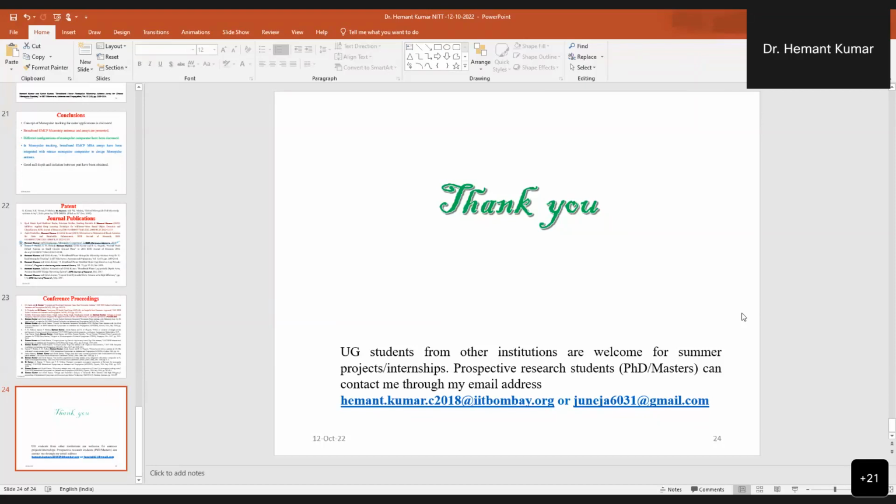There are other substrates available: apart from 5880, we have 5870 also, and there are two or three more substrates. Arlon is also one of the substrates, and Arlon's dielectric constant is also low. But the main thing is, if you want less dielectric loss, the loss tangent should be as low as possible. But to get a lower loss tangent, you have to pay more money for the substrate. So the substrate will be costlier.